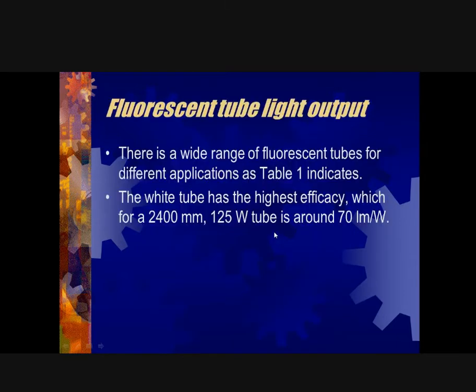Now, the output of the fluorescent tube: we consider the fluorescent tube to have a really high efficacy, very efficient. Actually, converting from fluorescent to LED in some cases doesn't make any sense unless the fluorescent goes bad, because the efficacy is so close that it doesn't really affect your bill much if we're talking about one lamp.